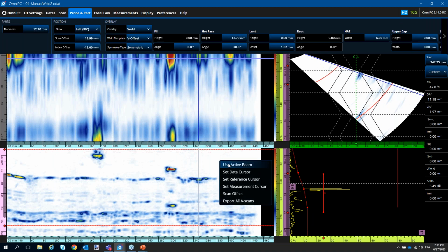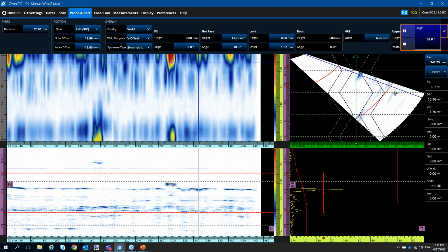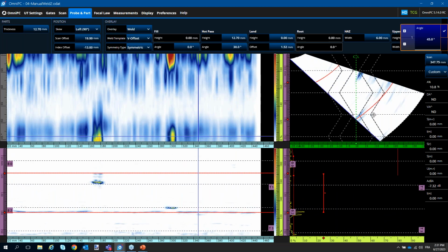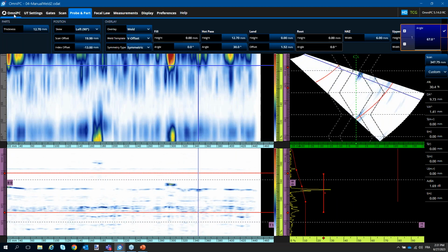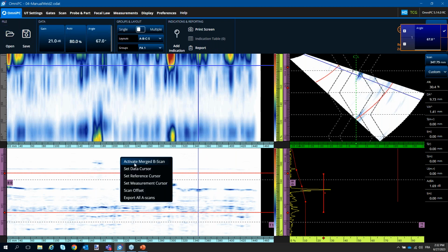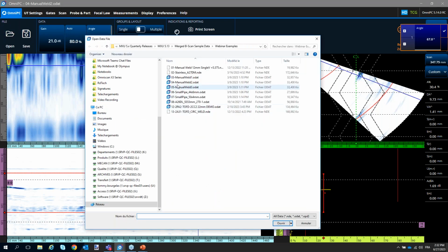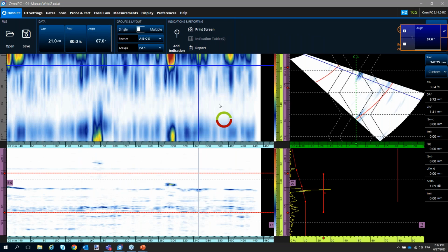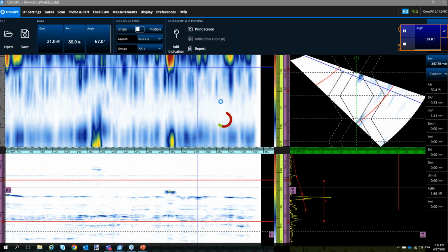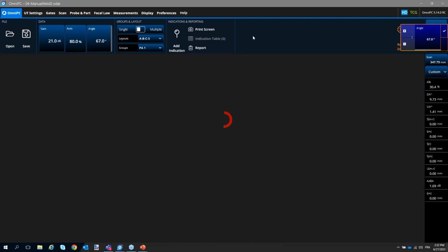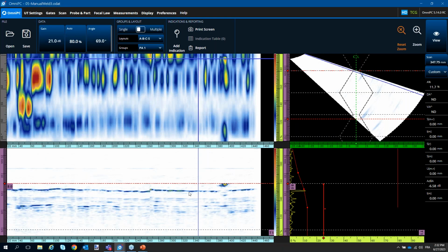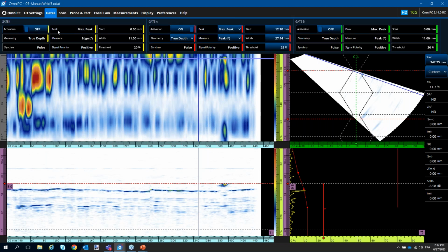And a last step is scrolling all B scans. Did I forget anything? Nope, I did not. So I'm good. So that's how I can use the combination of merge B and not merge views in order to alternate between merge and non-merge. Depending on the weld, some welds that have so few geometry echoes may allow to void the streaming, the B-scan scrolling portion. Personally, I always feel safer to keep it, just to make sure if I'm going to call an indication, I don't forget anything.